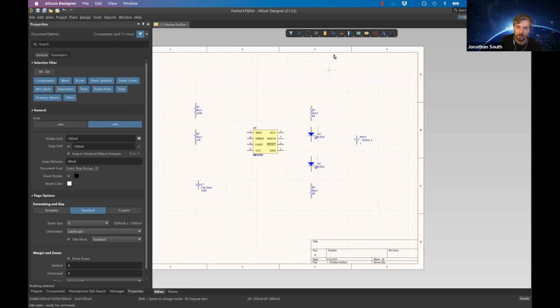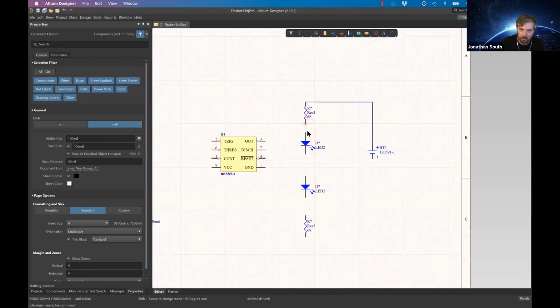basically wiring things up. So up in the top of your circuit schematic, you'll have a quick toolbar. The wavy looking one is defaulted to wire, but you can click and hold on those toolbars to bring up other options. But yeah, we want the wire, and that's going to look like a little crosshair. And we just start wiring things up from the nodes as needed. It looks like it's going to go red as we join up nodes. And scroll in, and just join things to things that they need to be joined to. Should be pretty familiar with this style of stuff if you've done any LTspice.